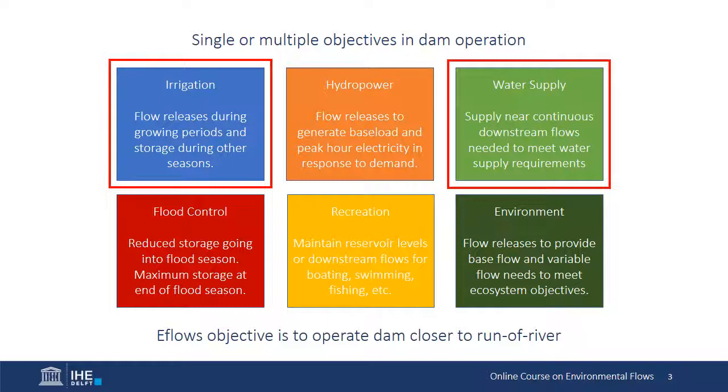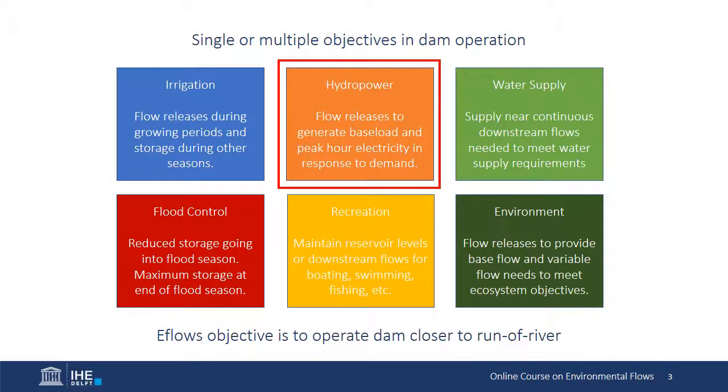Water for irrigation and domestic or industrial supply may also be delivered on weekly or daily timescales depending on the level of intermediate storage water providers possess. The highest resolution temporal variability in water demand comes from hydropower, which varies on hourly timescales. Because electricity generated at hydropower plants is delivered to users at near the speed of light and storage is limited in the system, the variation in demand depends on the rapidly changing needs of the users.